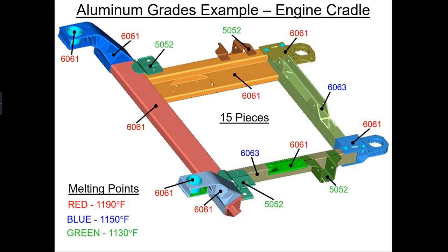We're trying to get the engine to roll underneath your feet in a front end collision. We're trying to get the engine to take the impact and give your body more of a chance to decelerate. So sometimes we'll use different types of materials in different places to give us a certain amount of strength.